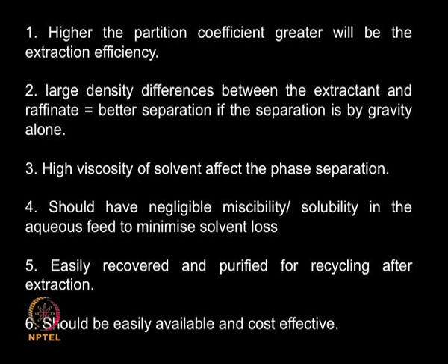Okay. So there are many other points which need to be considered when you are performing a liquid extraction. Higher the partition coefficient, greater will be the extraction efficiency. Here a very large number means extraction will be very good. Large density difference between the extractant and the raffinate, you can achieve good separation using gravity alone. That means after the mixing you can allow them to settle from each other, so you will get a very nice phase separation because of gravity. But if the density difference is smaller, then you may have to resort to some sort of a centrifugal separation.